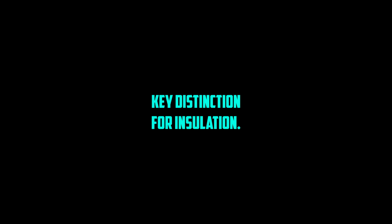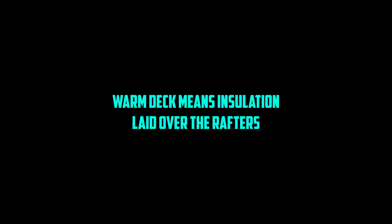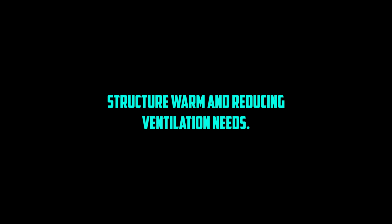Energy saving in roofs. Cold deck versus warm deck. Key distinction for insulation. Cold deck means insulation at ceiling level, joist level, leaving the roof space itself cold and needing ventilation. Warm deck means insulation laid over the rafters, directly under the roof covering, keeping the roof structure warm and reducing ventilation needs. Preventing condensation is vital. Either use a vapor control layer on the warm side of the insulation or ventilate the cold space effectively. Vapor check plasterboard can help act as that vapor barrier.